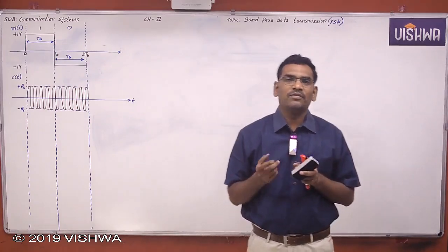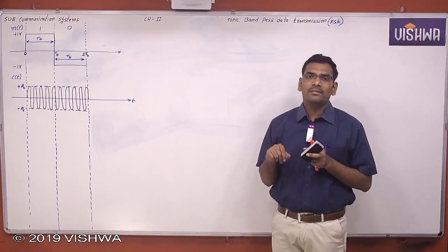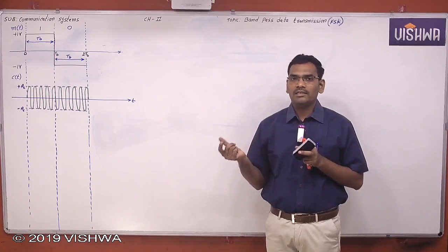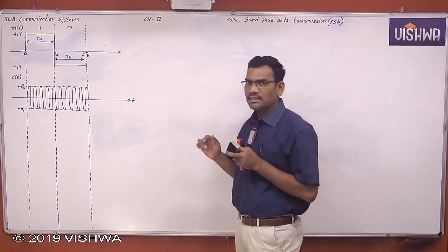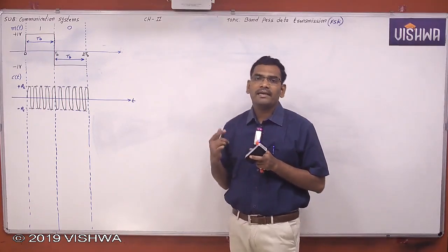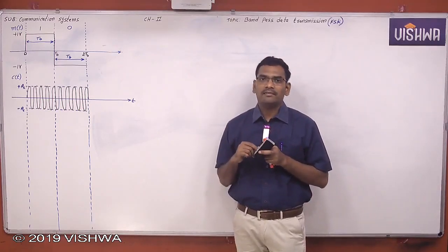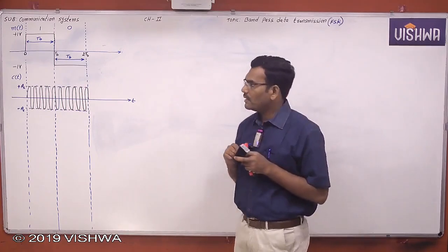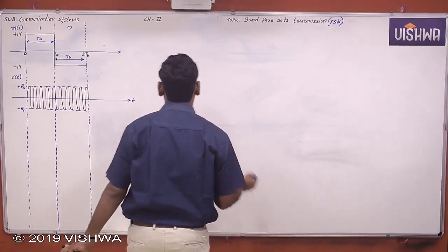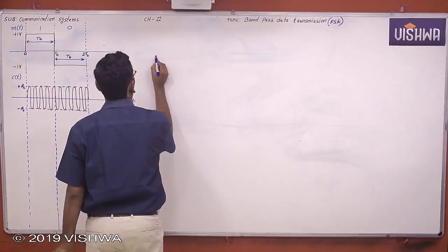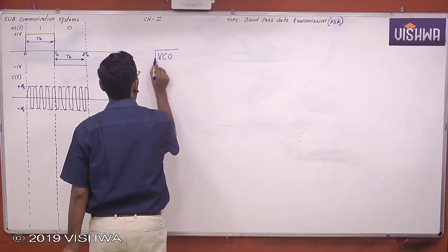Frequency shift keying is similar to FM. Each voltage will be converted to a frequency, so this is also a voltage to frequency converter. Whenever you think of a voltage to frequency converter, one technique we already completed is the voltage controlled oscillator, VCO.